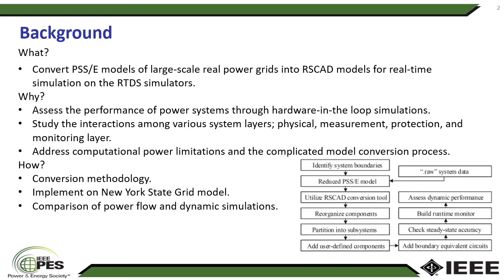In order to achieve this, we first propose a conversion methodology, and then we implement this methodology on the New York State grid model, and finally we provide some comparison between power flow solutions and dynamic simulations between both PSS and RSCAD. In the following figure, you see how the conversion process takes place, starting from the PSS model and ending up with the dynamic performance. However, many of these items pose challenges which will be addressed in the following slides.